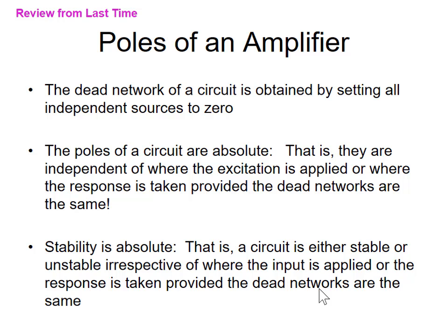One determinant is in the numerator, and what you do is you replace some column in that vector. Let me do it differently now. Let me look at some voltage here, Vk, one of the voltages here. And so what you do is you take this matrix and you look at a determinant, and the determinant is obtained by replacing, I believe it's column k, by the excitation vector. And the rest of the entries in this determinant are the Y matrix values.